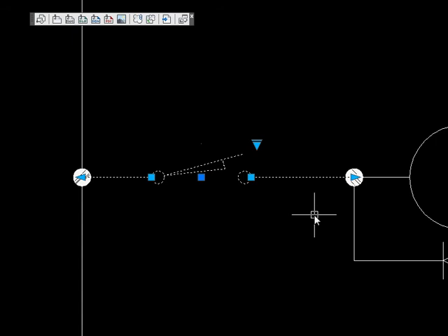We're going to use a held normally closed. Just as a real quick side, what that means is it's a normally closed switch, but it's held open by something, perhaps by a shut door, like a door to an enclosure of some kind. And it all depends what you're desiring for in your elementary wiring diagram. But the thing about this limit switch and a lot of dynamic blocks, and blocks in general, is once you've drawn them, save them as a block. Use it time and time again for consistency and productivity's sake.